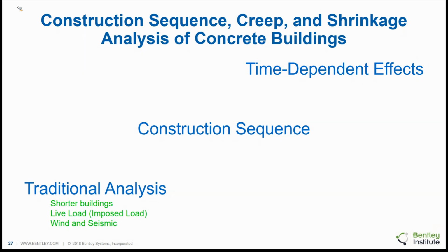That traditional analysis is certainly valid for your live load case, because that's the way the live load actually is applied to a building. The building is erected, and then people and desks and things are moved into the completed structure. And the traditional analysis is certainly adequate for wind and seismic, because even for the time-dependent effects, the wind and seismic loads are transient. They're there only for a very brief period of time, and then they're not there anymore.